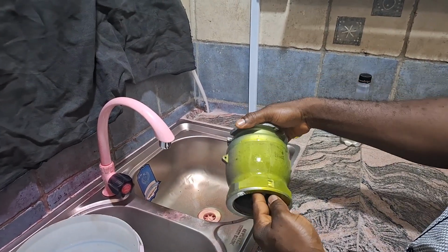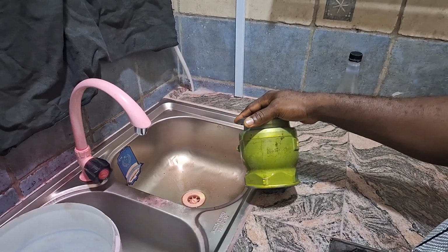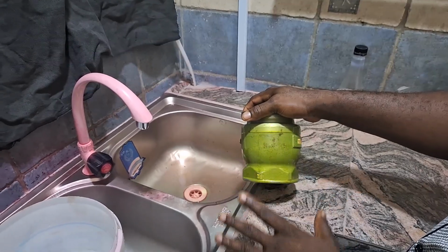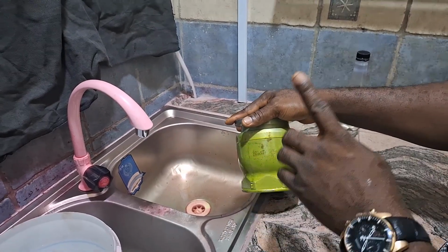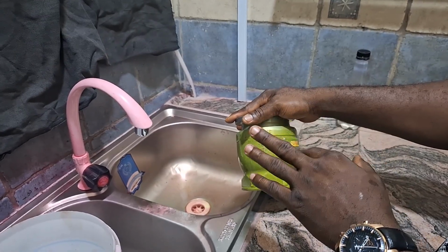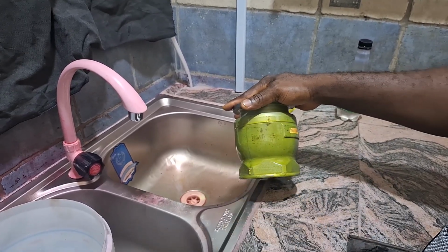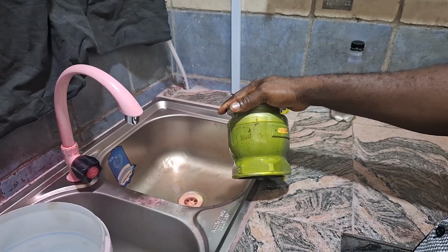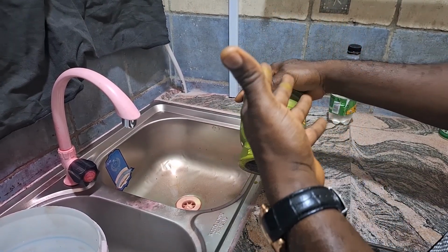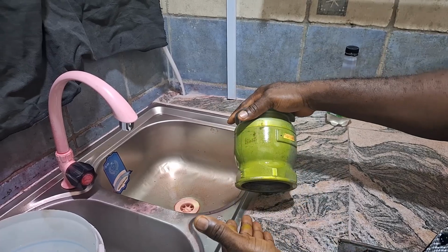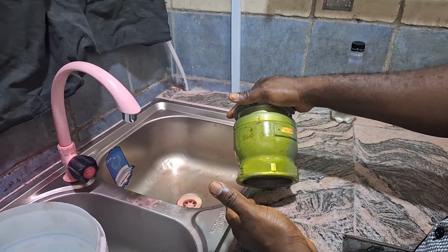In the case of the post-emulsifiable, lipophilic, and hydrophilic, what differentiates it from the other two methods of penetrant removal is that it requires an emulsifier. So basically, what does the emulsifier do? You have your penetrant and you want to remove it with water at the end of the day.